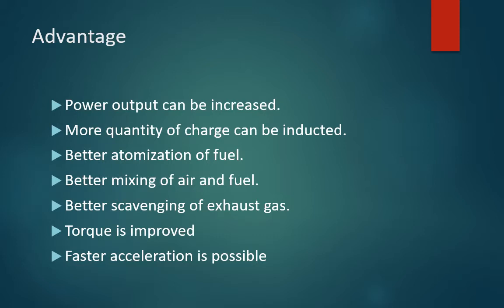We can immediately observe that by supercharging we get more torque or power output for the same displacement, for the same cylinder volume, right? You get the point? We get more power output or torque, and we can increase the power output of the engine without doing much modification to the engine itself. Remember that for the same cylinder size, the specific power output per unit area will be increased. In other words, the specific power output increases and we get more power output for the same engine size. Am I right?